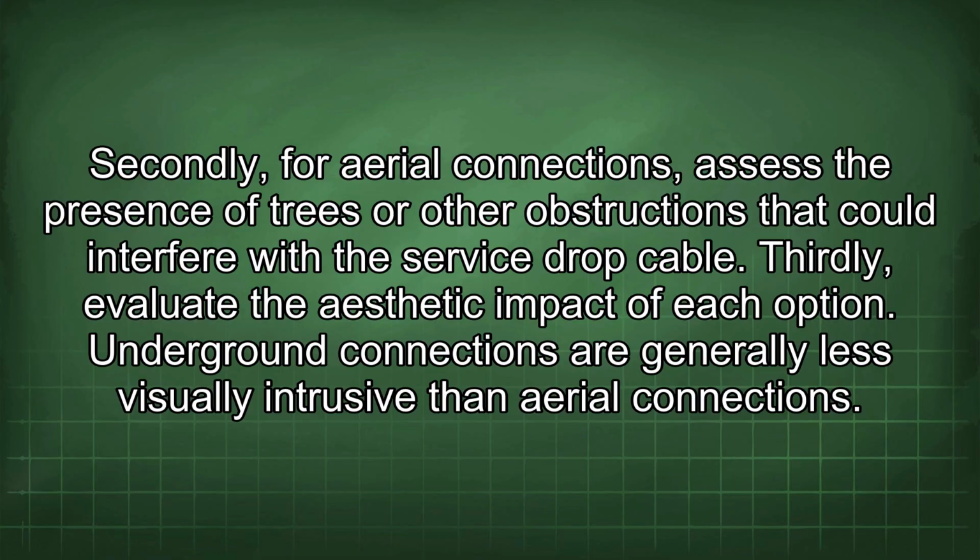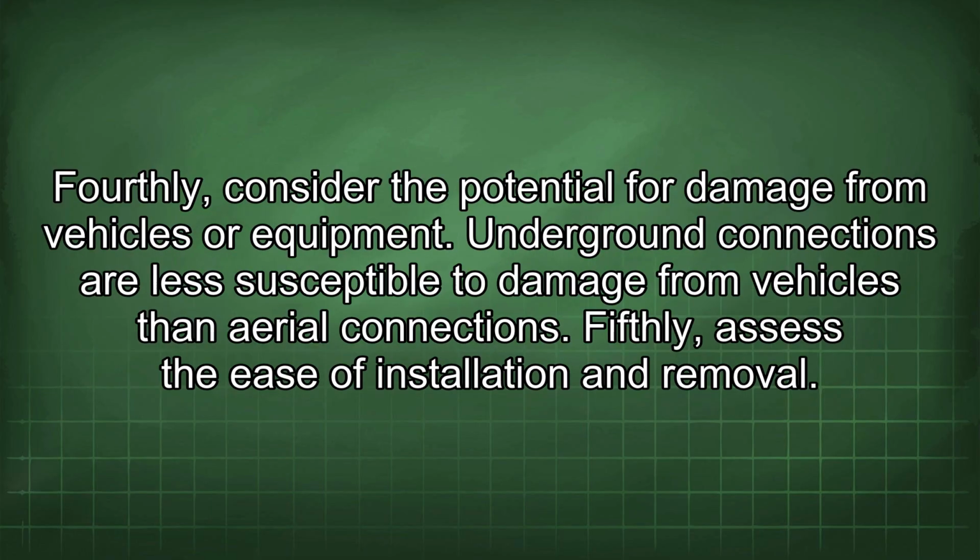Thirdly, evaluate the aesthetic impact of each option. Underground connections are generally less visually intrusive than aerial connections. Fourthly, consider the potential for damage from vehicles or equipment. Underground connections are less susceptible to damage from vehicles than aerial connections.